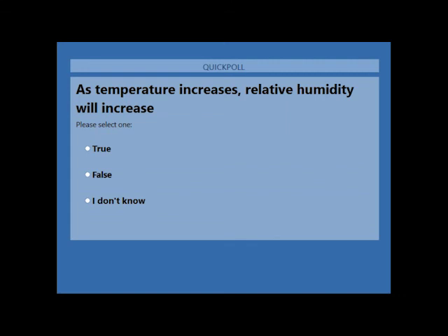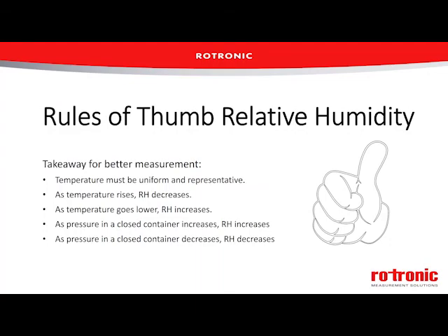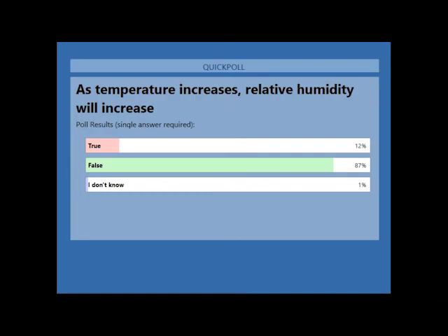And he was complaining. He said, "You send me this new probe, and it's supposed to be calibrated, but it's not. It's way off." I watched him do it, and sure enough, he put half of that probe in the chamber at 40 degrees, the other half of the probe was out in the room at 23 degrees, and he was getting that 3-4% error. That's a very common issue, especially since if you did that same test at 23 degrees C, everything would read correctly because there's no temperature gradient. So a calibration setup or a test setup that works in two equal environments is very different than when you've got that temperature gradient between the two.